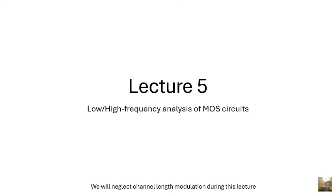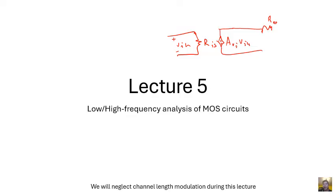Okay, so last lecture we concluded our small signal analysis. In particular, we said that for each individual single stage amplifier, we found out how to make an equivalent circuit model that included an input resistance, a gain, which is a voltage controlled voltage source plus minus V in, and then an output resistance R out.